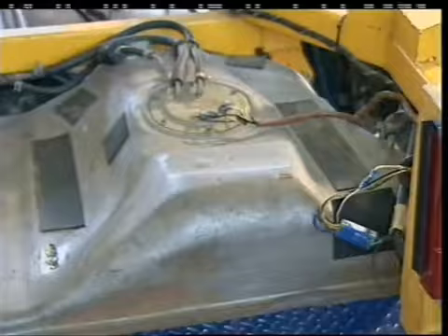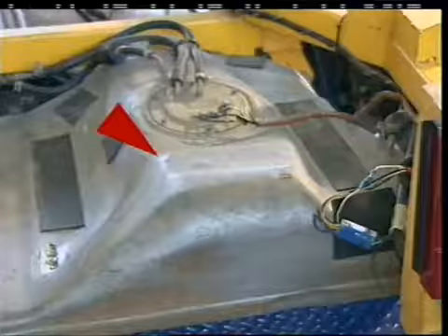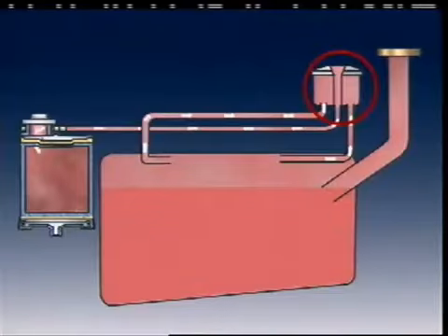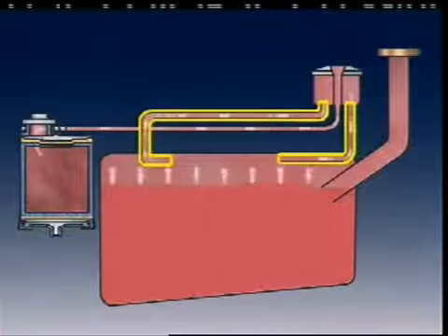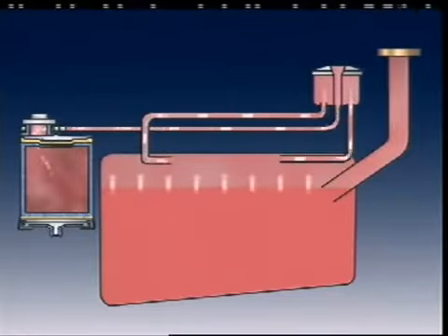Modern tanks also contain an expansion volume either directly in the shape of the tank or in a separate chamber connected to the fuel tank by tubing. A liquid vapor separator may be connected to the tank by a number of tubes. This separator allows liquid fuel to separate from the vapors and return to the tank.